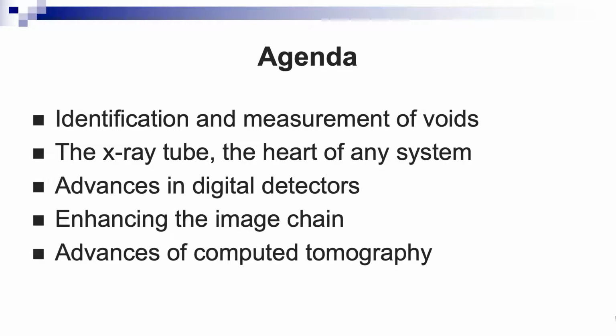So I drew a few little sketches and explained to him the process of assembling the board and how you were never going to get 100% void free in that central pad. And he said, oh my God, I never realized this. I just worked with the numbers off the data sheet and didn't put in any margin for error or voiding. So yes, voiding becomes more and more of an issue.